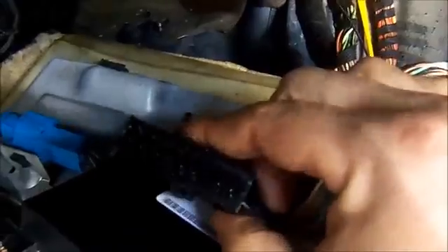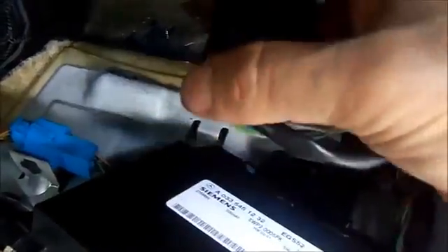Okay, here I'm inside the vehicle, and as we can see here, these wires are saturated with transmission fluid as well. There's a spot of transmission fluid there, and this TCM connector that goes to the solenoids is also a little wet with transmission fluid. It did not protrude inside of the TCM. It's a little moist, but it did not go inside of the TCM. I already opened this up, and it's dry inside. But the connector is wet with transmission fluid.